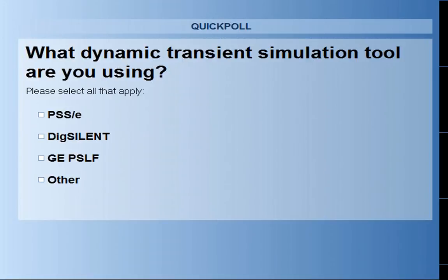We have the ability to integrate user-defined models developed in Simulink, and to integrate ePHASORSIM with SimPower system controller blocks as well. In terms of the actions that can be triggered in the network, we can have balanced and unbalanced faults. We can have open connector conditions, line tripping. We can have generator outages, fault on transmission lines at any point of the line, load shedding and restoration events, tap changing events, automatic voltage regulation adjustments, reclosing commands, loss of excitation, and many more.